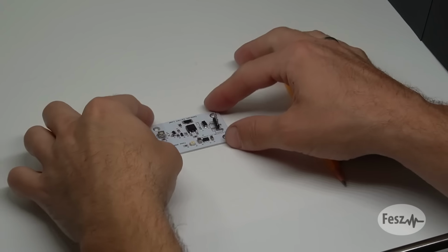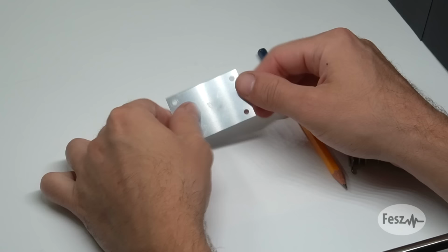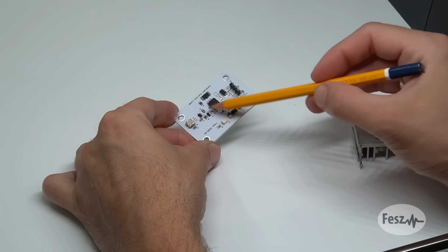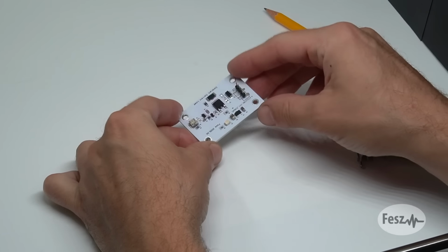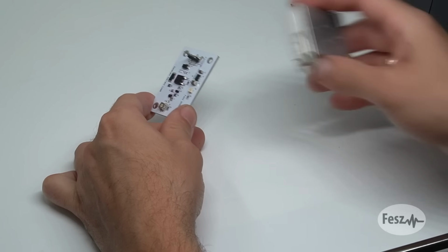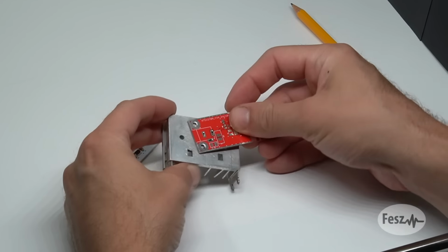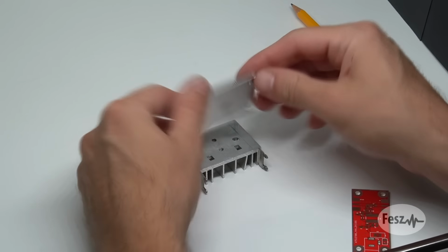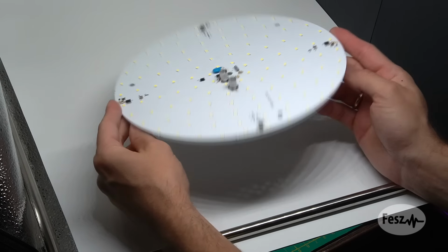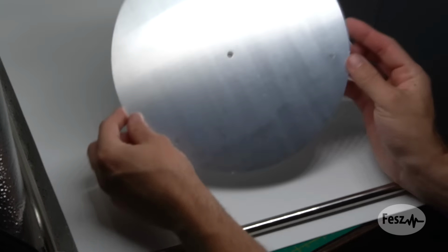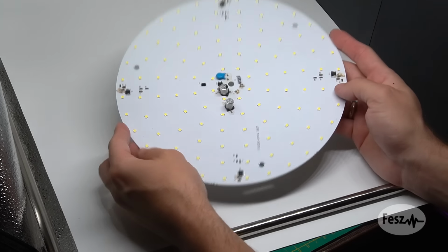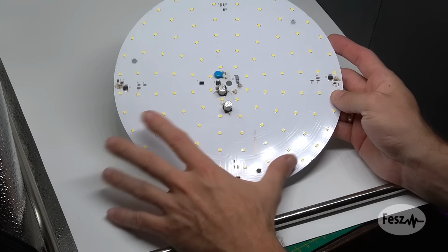But what if you didn't have to separate the board from the power transistor and heatsink, and could just bring everything together? So the special thing I wanted to try on this build is to use aluminum substrate boards to contain both the driving circuit and the power transistor, and then to dissipate the power through the board to a heatsink. You could do this with a normal FR4 board and a bunch of thermal vias, but aluminum is far better at this. It's quite a common practice in lighting fixtures, but it also does come with the downside that the layout typically needs to be a single layer.